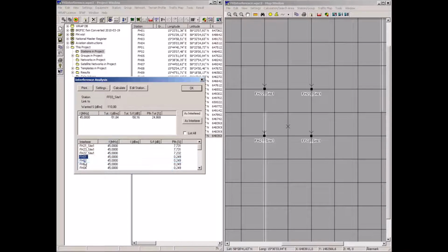The others, the more remote frequency hoppers, give each this contribution 0.249%, and that is just 1/401, since they hop on 401 frequencies at any instant in time. Looking at a single frequency, the probability that the hopper is on that frequency is 1/401. So that's why we get that value. And again, the fixed frequency interference level is calculated, and it may be interference if they really are supposed to operate in different nets, or it is actually wanted signal level if they are in the same net.